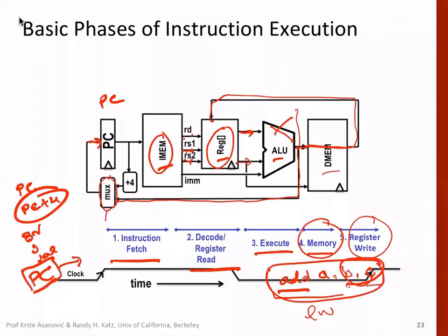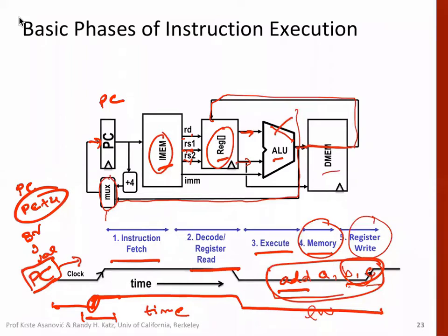Okay, so this is the clock timing. It has become a little dirty, so you can see that it's the time. Now this simply represents a clock. Note that when the clock is high, at the rising edge or positive edge, we have to do all the writing into state elements. And for the rest of the time, once we have done this, all the time is available for the combinational logic circuit to do its job. Okay. Any question? All right.